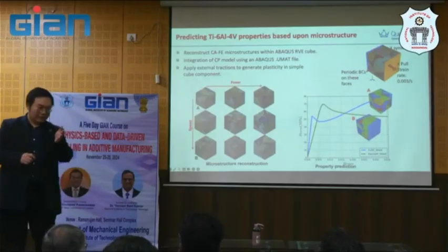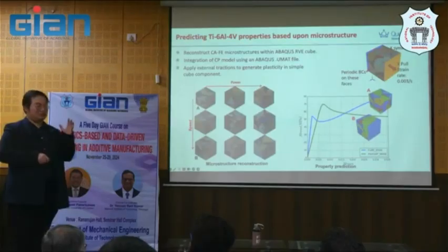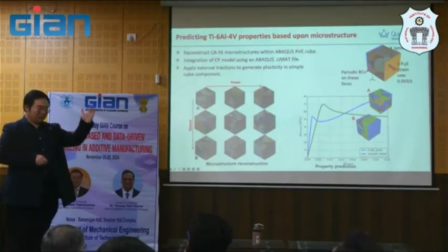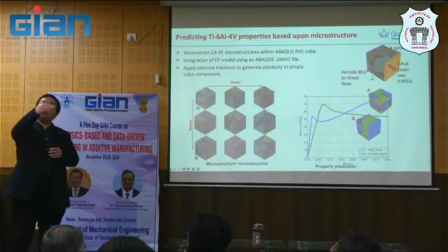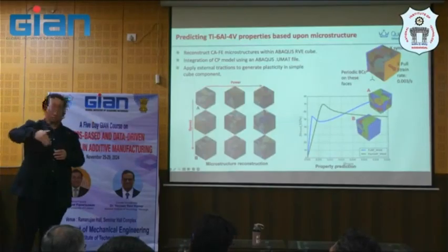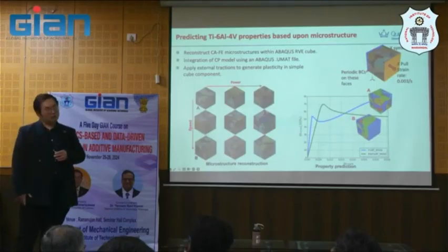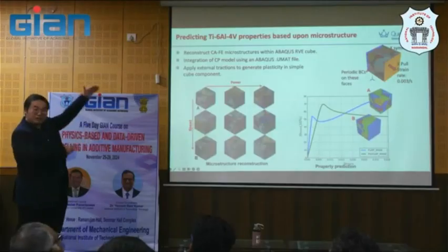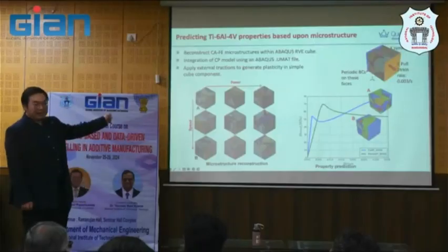That is an assumption made. This structure assumes a prior beta grain. So we assume that the deformation takes place during beta transformation. Because after about 950, or 850 to 950 depending on the different grade of Ti-64, the beta will transform to alpha, right? And then we assume that deformation takes place just before that. That is the assumption made in this case.